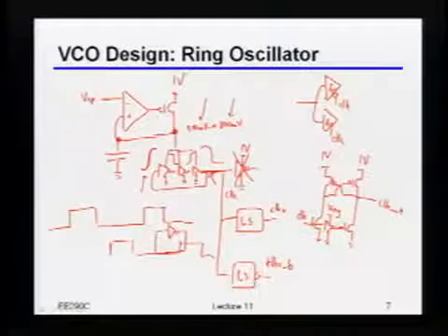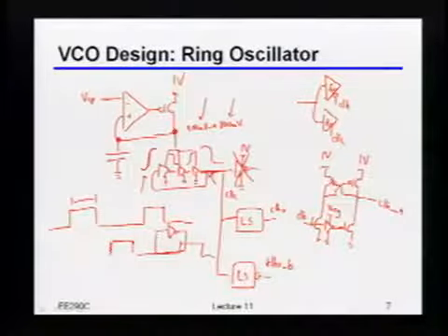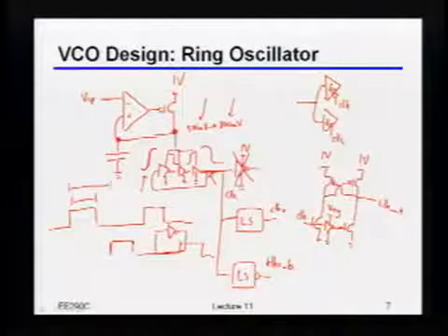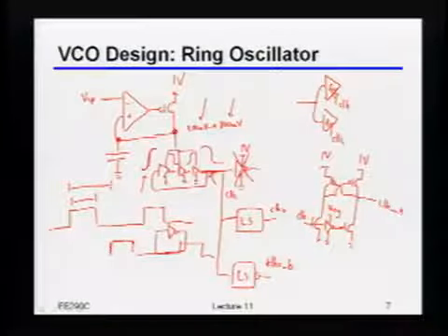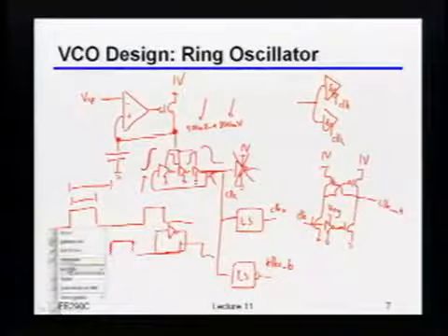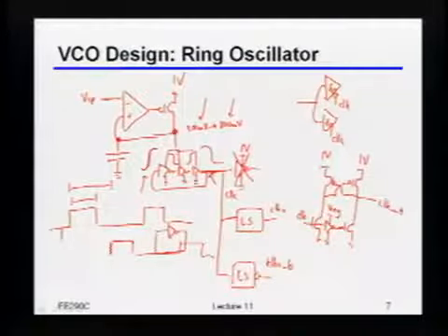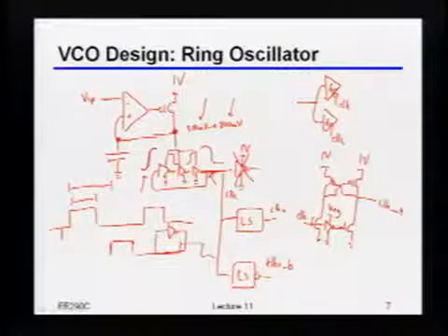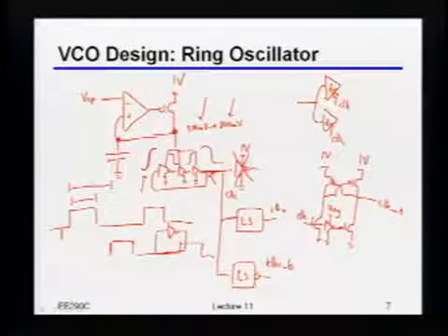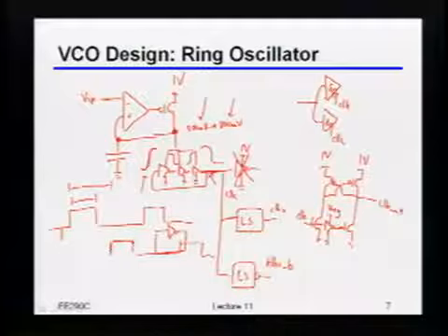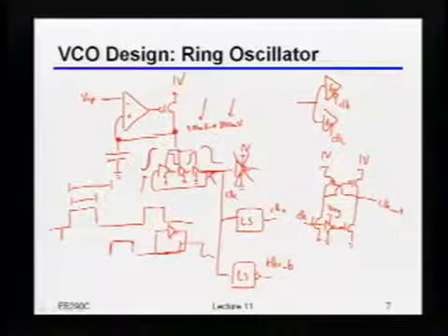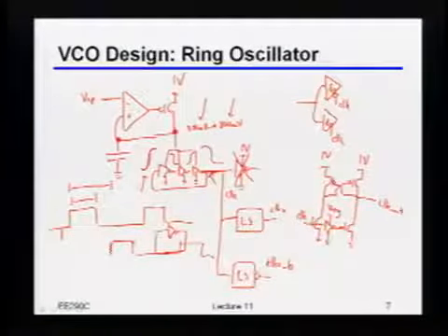So in other words, each individual duty cycle is still wrong, but the spacing between the two edges will be correct. Okay? In this particular example that I've drawn here, having at least the spacing between the edges be correct is better than having both the bad duty cycle and the incorrect spacing. Does that make sense? Or more questions on this?